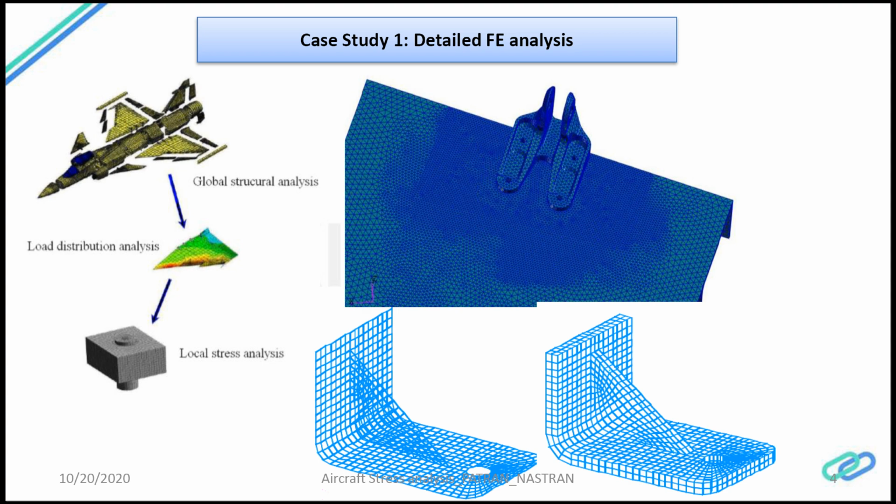then the fasteners, bolts, and brackets like these will be modeled using 3D elements. Why do they model these brackets and fasteners with 3D elements? To capture accurately the load distribution at the interface locations. When I say interface, it means attachment or connection locations, connecting something to something.